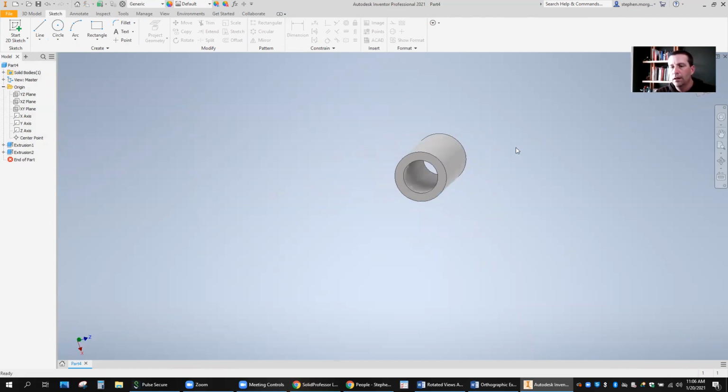And we've got a basic cylinder section. So, all right, that is kind of the basic workflow. You start with a sketch, you fully define that sketch, then you move on to your 3D model tab, where you can extrude or extrude cut or perform another 3D modeling option.